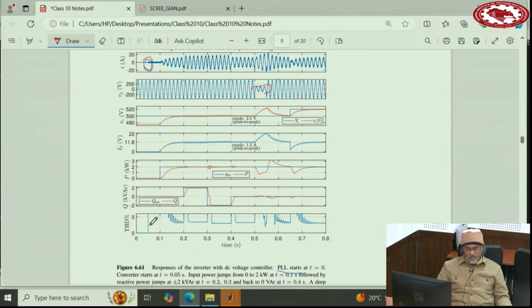This shows the THD, total harmonic distortion of the current. Remember, we chose RP equal 5%. That is the reference of the current. We allowed 5% distortion, double frequency on it. And I said it will convert to harmonics on the AC side.